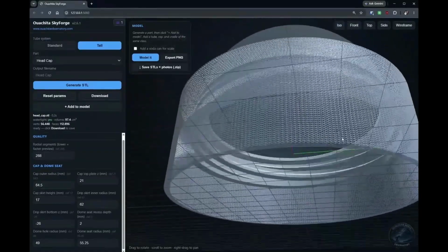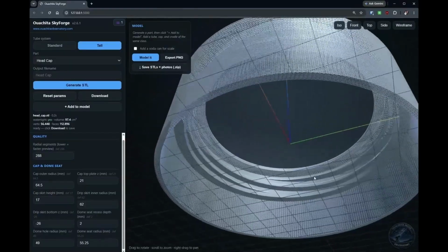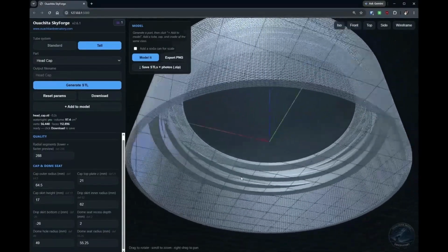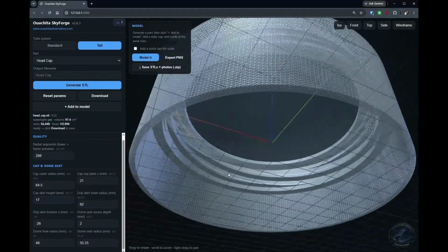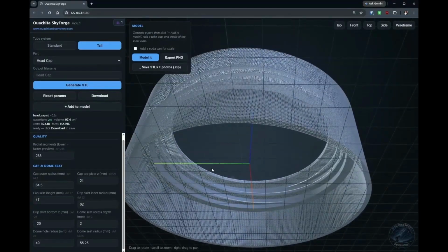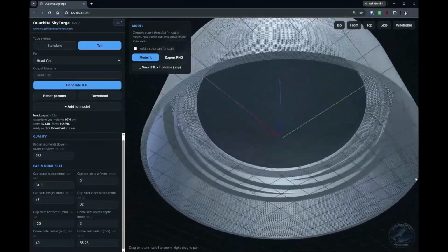And one thing to notice, you'll see these threads have multiple starting points, so that gives you the option to have a quicker tightening. A 27-degree turn completely tightens this lid down. So you have a thread start there, there's another one there, where some screws have one single start thread. This has 3 different levels where it can start at, so it just allows you to start tightening things faster.